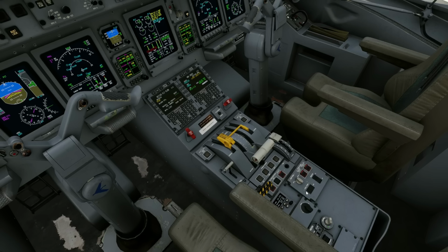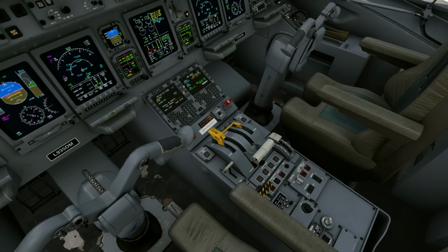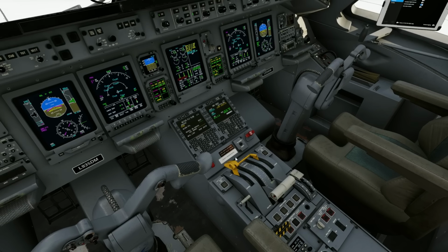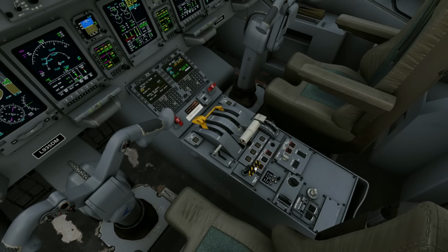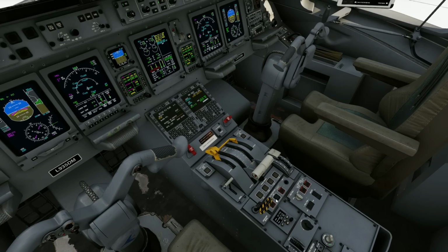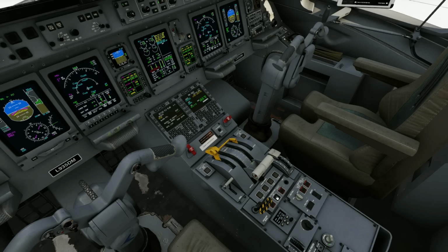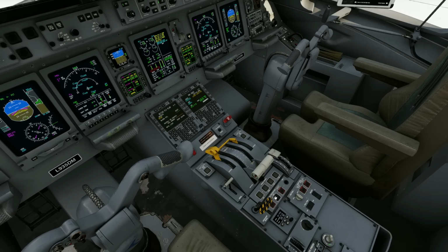One of the last few things I want to highlight here before we go ahead and get this thing turned off is the new stall protection system. So once again, I'll pull the stick all the way back, release it, Gust Lock's free. With the new stick pusher and stick shaker, we have simulated the stick pusher in the 145 and the stall alarm. Before every flight, we test the stick pusher to make sure that it works. That's done by holding the yoke back, releasing the Gust Lock, and moving this to the full yoke, full aft position.